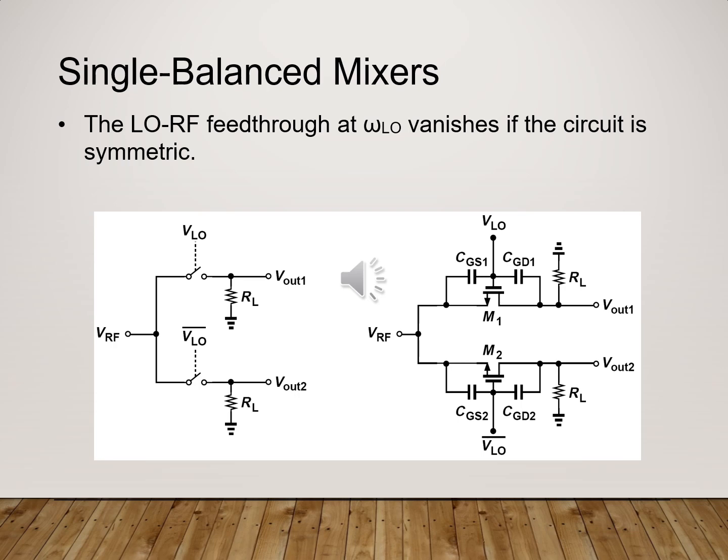Now, the single balanced mixer provides either local oscillator or RF rejection at the intermediate frequency output, but to be fair, it requires a higher local oscillator drive level.